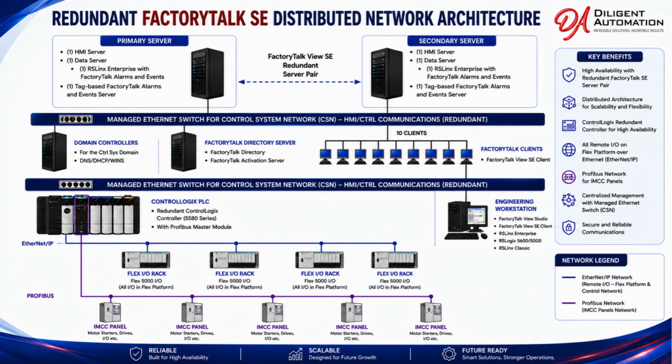The PLC is an Allen-Bradley ControlLogix L73 controller with all remote I/O on the 1734 I/O platform. The project includes approximately 2,500 digital and analog I/O points, making it a large-scale industrial automation system. In addition to the remote I/Os, the plant contains 8 intelligent MCC panels, comprising approximately 400 intelligent motor starter devices, including direct online starters, soft starters, and variable frequency drives.